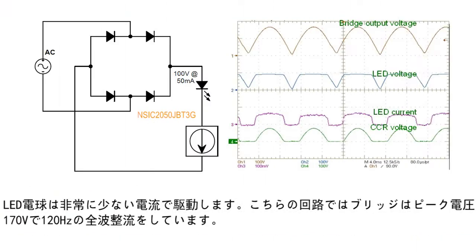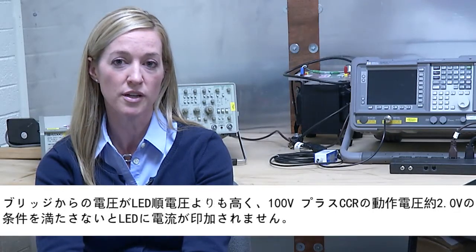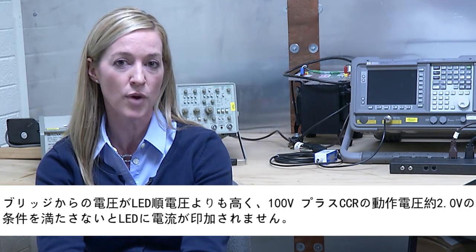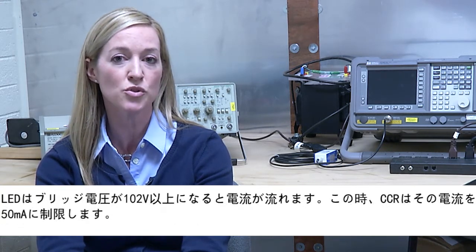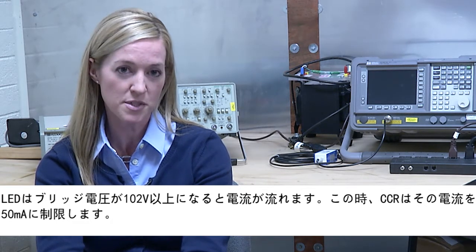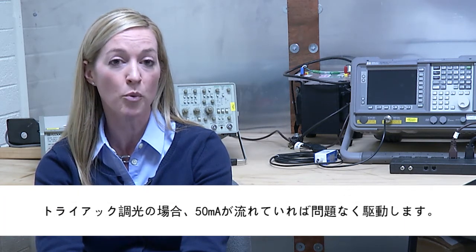In the circuit below, the bridge provides a semi-sine wave at 120 Hz with a peak voltage of 170 volts. The LEDs will not draw any significant current until the voltage out of the bridge is above the forward voltage of the LEDs, 100 volts plus the CCR regulation voltage, which is approximately 2 volts. The LEDs will draw current when the bridge voltage is greater than 102 volts. The CCR will then limit the current to 50 milliamps.